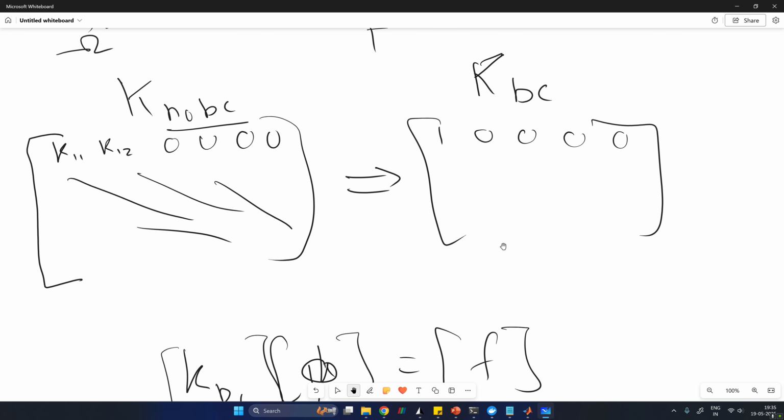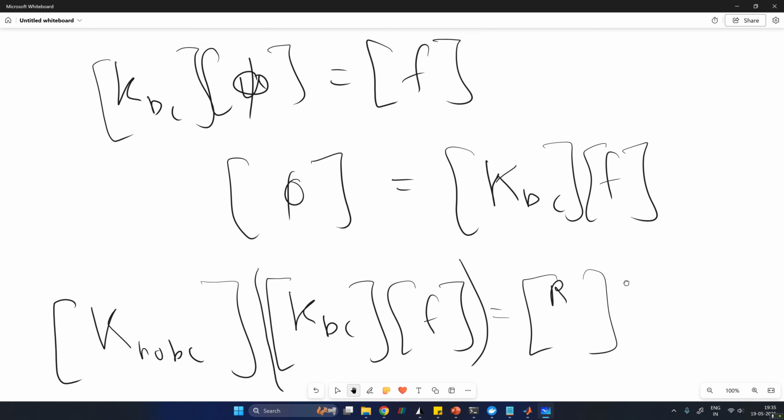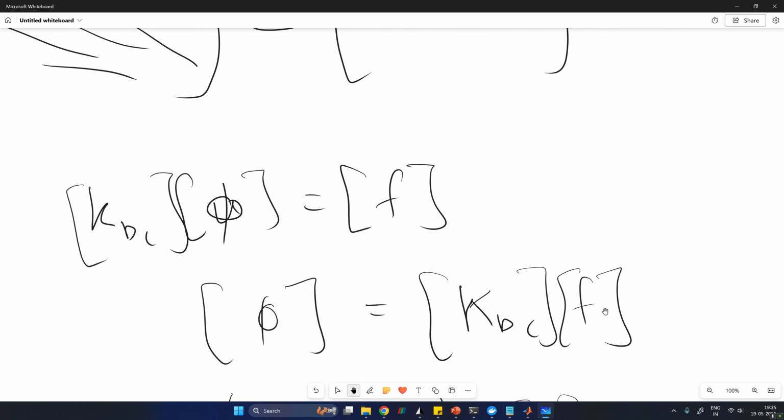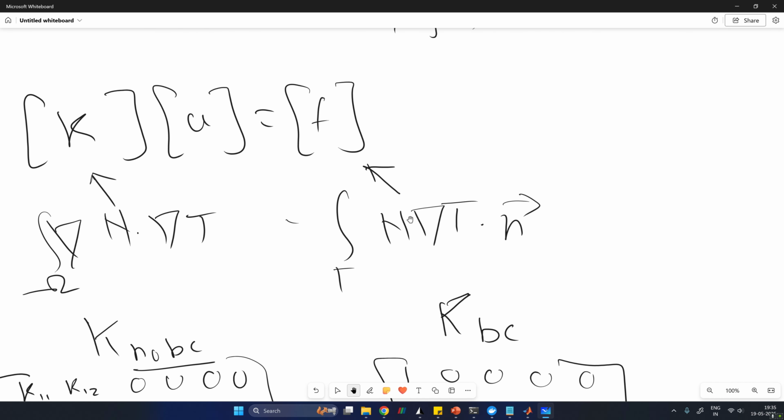Okay, so these come out naturally just like a force vector, because this is basically just your phi, right? So this is just another system which is your bilinear form multiplying your unknowns vector. So you just get a force vector here on the RHS, and this force vector is also having this n here, right? N into del t. So it has exactly this form, and so you are actually getting a direct integral out as nodal values here. You don't have to perform the boundary integral. You directly get these kind of values, and you just take the sum.